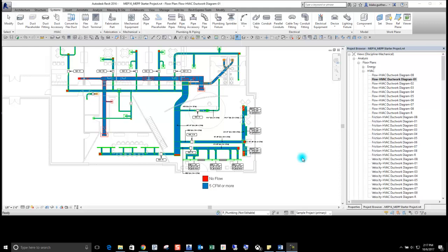done, getting the calculated airflow into Revit, either running the loads in Revit or using GBXML to get that. And then once your air terminals have the proper airflow and systems are connected, then we're able to use Revit to size those systems. So if connections aren't made, if parameters aren't set up, connectors aren't set up correctly for flow propagation, none of this is possible. So this is all based on that all being set up.